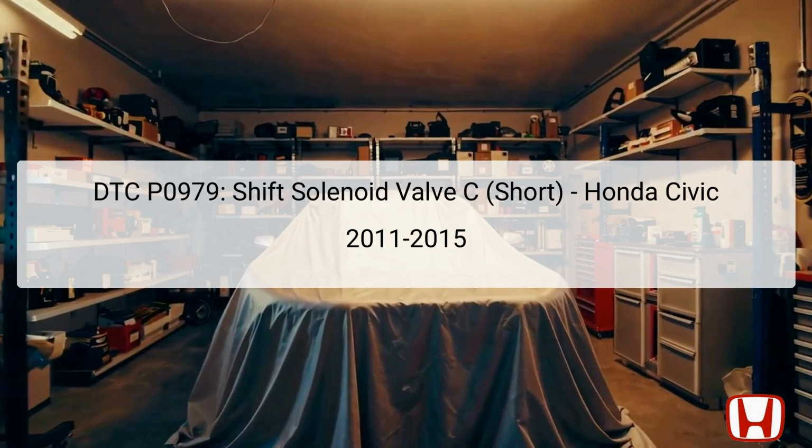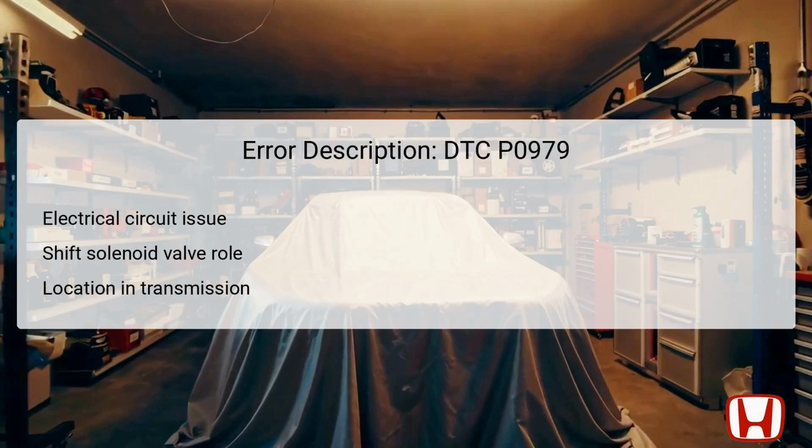Throughout this guide, we will discuss the symptoms, possible causes, and detailed troubleshooting steps to accurately diagnose and resolve the issue. DTC P0979 indicates a specific fault in the electrical circuit related to the shift solenoid valve C. The shift solenoid valve is responsible for modulating the flow of hydraulic fluid within the transmission, thereby enabling appropriate shifts between different gears. This valve is usually located within the transmission assembly, often near the valve body, which is integral to the gear shifting process.